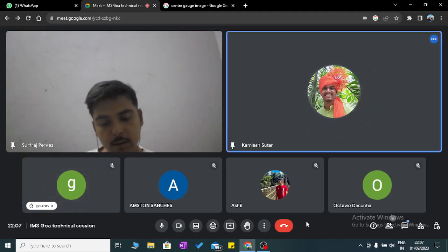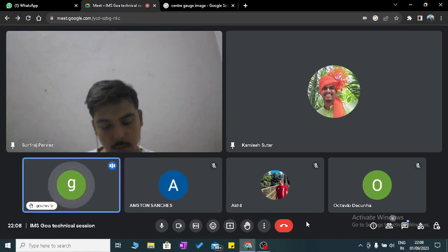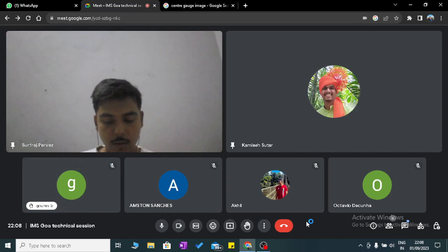Okay, while milling, drilling, tapping, and turning, a soluble oil coolant is used, which has a 70 to 90% water to oil ratio. So I think it's a mixture. You can make this liquid coolant as per the requirement of the material which will be machined. So any other questions regarding this? What is speed? We already completed that part.